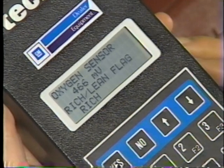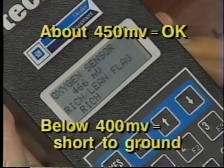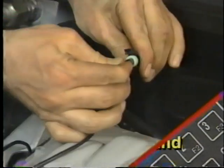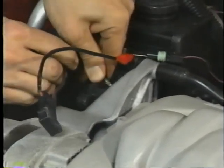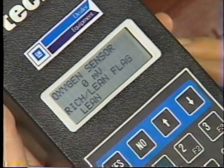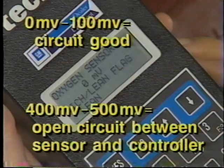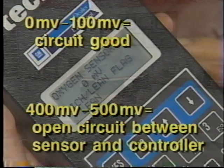Measure circuit voltage at the controller. It should be close to the reference voltage. If it isn't, the circuit is most likely shorted to ground. Next, connect a jumper between the sensor wire on the controller's side of the circuit and ground. The voltage should drop close to zero. If it does, you know the sensor circuit is good. If it doesn't, there is most likely an open in the circuit between the sensor and the controller.